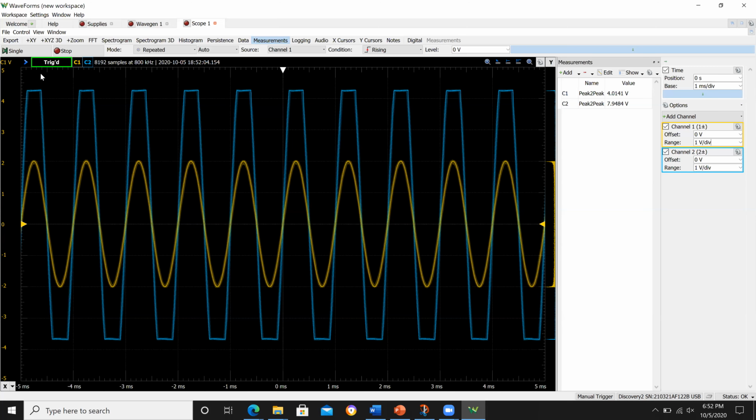The positive supply you can get a little closer, the negative supply you can't get as close. So that's a good thing to know, right? If you're trying to center up your signal, maybe on the output, and achieve maximum signal swing, maybe you want to shift this up or maybe you want to shift it down depending on the conditions of the circuit you're working with. All right, so that is clipping.